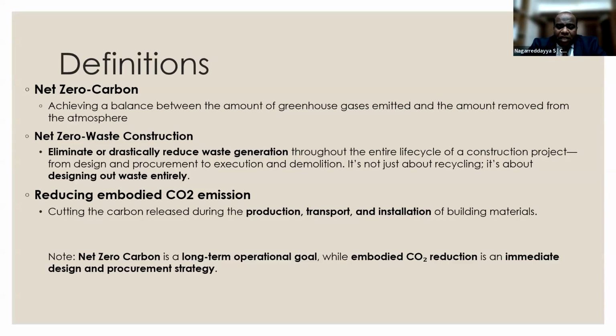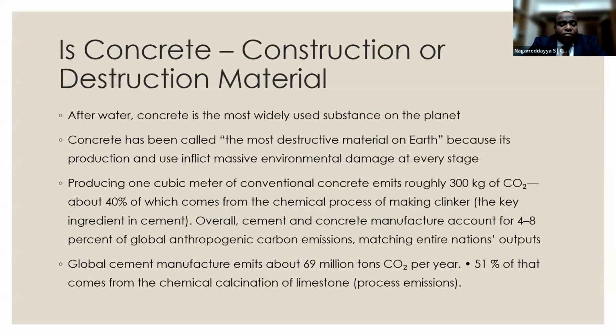So that is designing the right concrete mix design using SCMs, as our panelists have already explained, and the selection of the right materials. I mean SCM, supplementary cementitious materials like fly ash, ultrafine fly ash, GGBS, steel slag, and procuring them from local plants.